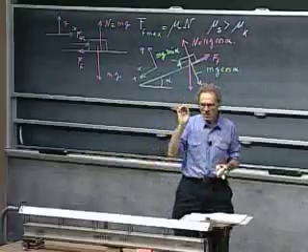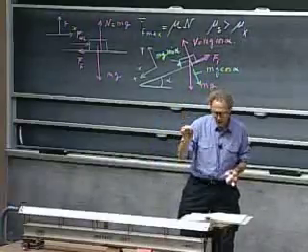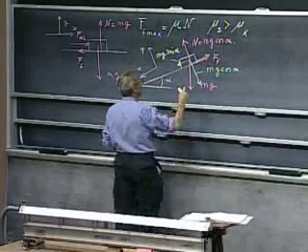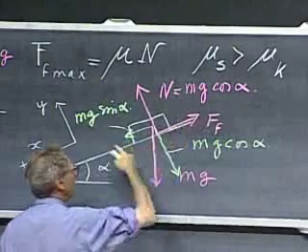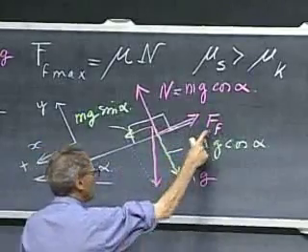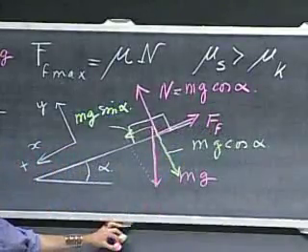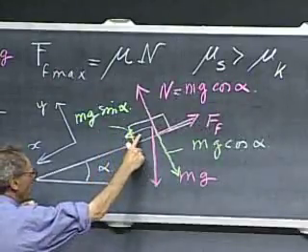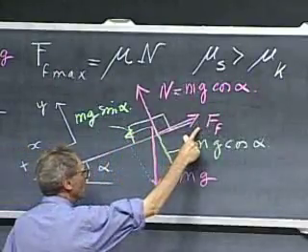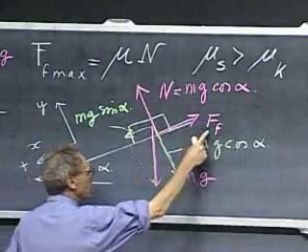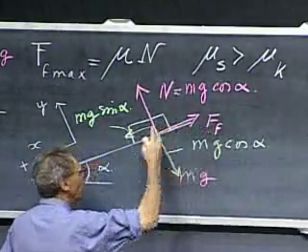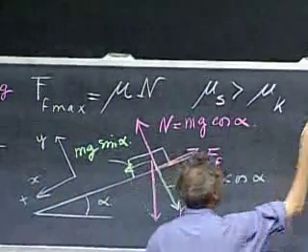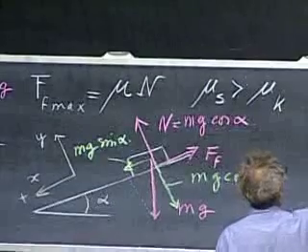Let us evaluate that very moment, that it's just about to break loose. I'm applying Newton's second law. In this direction now, the acceleration is still 0, but the frictional force has now just reached the maximum value, because I increase alpha, so this component will get larger, and this component will get larger, this component will get larger, this component is still holding its own, but then all of a sudden it can't grow any further, and it starts to accelerate.